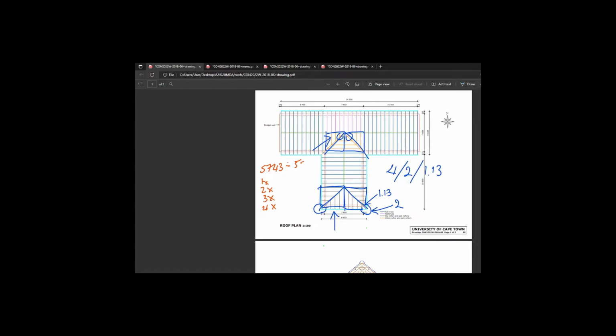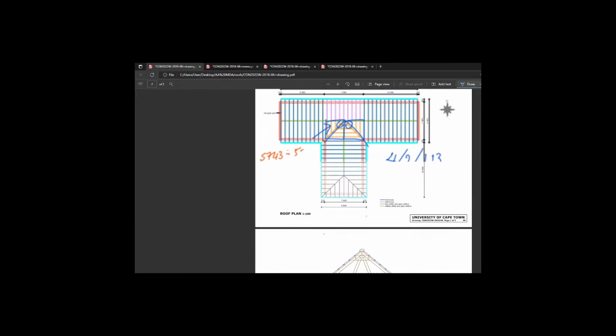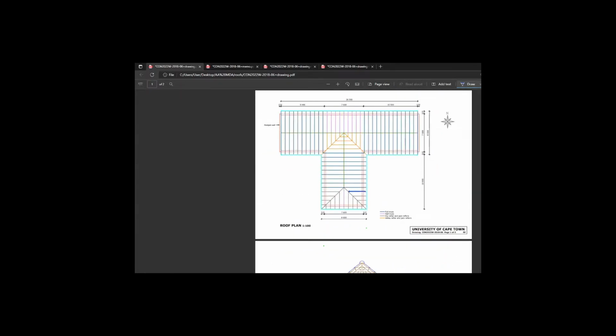Hoop iron roof ties. It is the same story as the half trusses, right? The roof ties are only fixed to brickwork and timber, so you have to take a look on plan and say, well, it's a jack rafter, so it's sort of floating in the air. It doesn't have the same structure as a full truss. It's by itself, slightly unsupported, and it's going to sort of piggyback onto other structural members. So our jack rafter, that's it. That's our drawing.